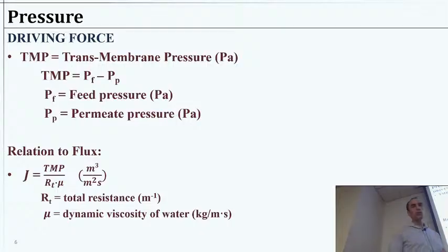So pressure that drives the membranes. We can relate the pressure to some of the membrane parameters. So when we think of the pore size of a membrane, we already talked about how if we restrict the pore size, it becomes hard to push water through it. And so we need to know how to work with that type of calculation, how to work with what's called the membrane resistance, what happens if it starts getting dirty and fouled, and how we can handle that.